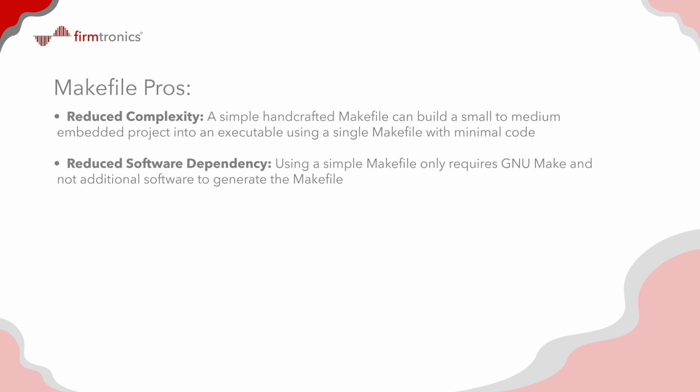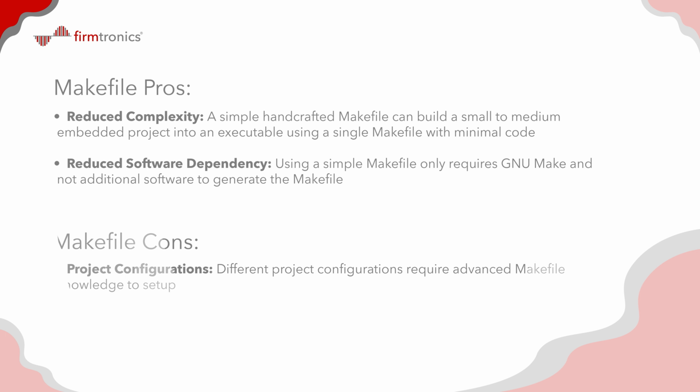So the pros are reduced complexity. A simple handcrafted makefile can build a small to medium embedded project into an executable using a single makefile with minimal code. Another pro is the reduced software dependency. Using a simple makefile only requires GNU Make and not additional software to generate the makefile. The cons are project configurations. Different project configurations require advanced makefile knowledge to set up.